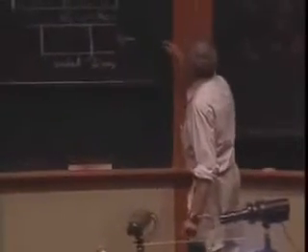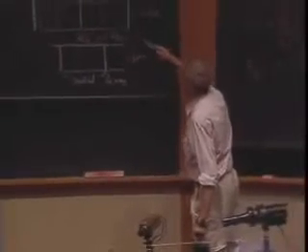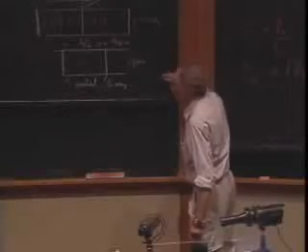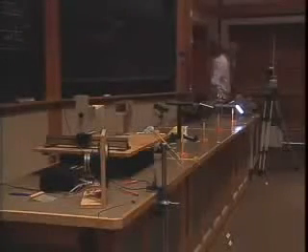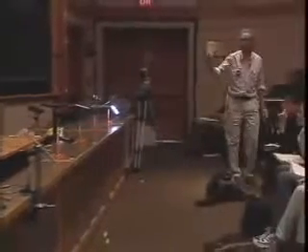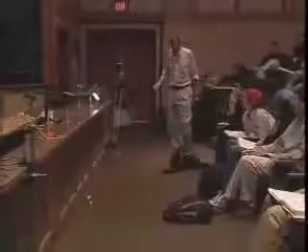But now what I'm going to do, I'm going to short this out here when I put the light bulb right in the middle here. So I'm going to put the light bulb at quarter wavelength. Now when I short it out at the end, I am no longer at resonance. You no longer meet the resonance condition which I meet now at an open end. Something that you can very easily verify. Now the moment that I'm no longer at resonance, I no longer have very high potential difference at the antinodes, which I had before when I was at resonance.